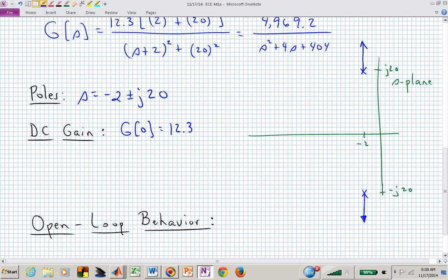So the peak time, now your natural frequency, and really the damped frequency, is what you can see is the piece of the natural frequency that's changing. So omega sub d is increasing. Your peak time, you'll get to your peak quicker, you'll have more overshoot, and now that may influence your steady state error, but you're not going to enhance your settling time at all by introducing a gain.